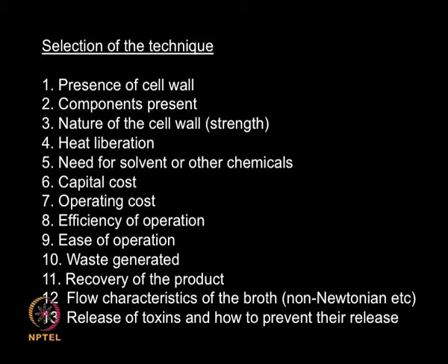Then flow characteristics of the broth. Once you have broken down the cells, the whole solution becomes non-Newtonian. As you know, non-Newtonian fluids behave very differently, unlike a Newtonian fluid. So when you apply more shear, the viscosity changes in a non-linear fashion. When you have a non-Newtonian fluid, it becomes very difficult to do the mixing, pumping, handling, flow and so on. So am I generating a lot of non-Newtonian fluid behavior once I have broken down the cells? You need to consider that aspect as well.